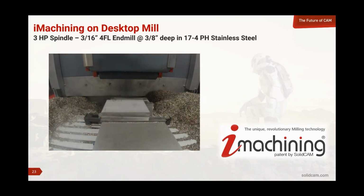Now, this is actually cut in 17-4 PH stainless steel. Now, PH stands for precipitation hardening. This material typically is in the low 30s Rockwell C in a pre-heat-treated condition. But if you work harden it by heating it up, you can take it up into the 42 Rockwell C range very easily. Notice we're cutting this dry. This is a 3/16 inch tool, and we're cutting it 3/8 of an inch deep. And we're doing this right now at 18,000 RPM and over 200 inches a minute in a 45-degree cutting angle.